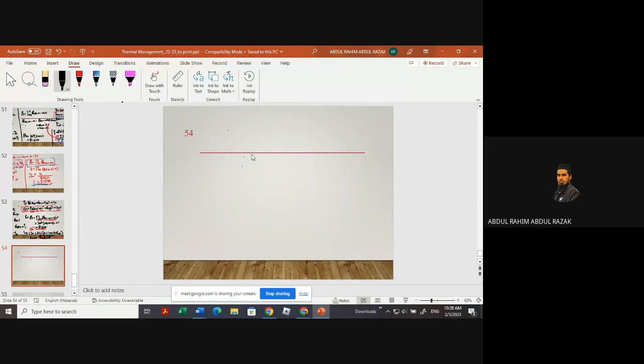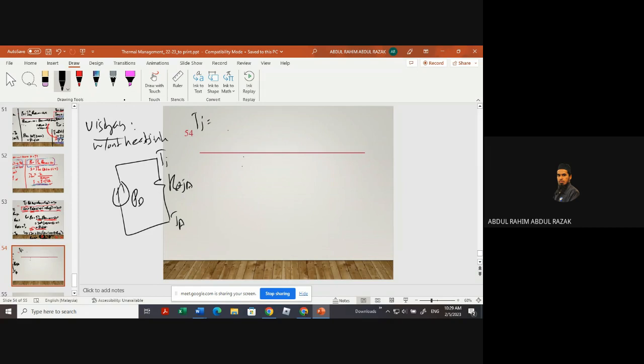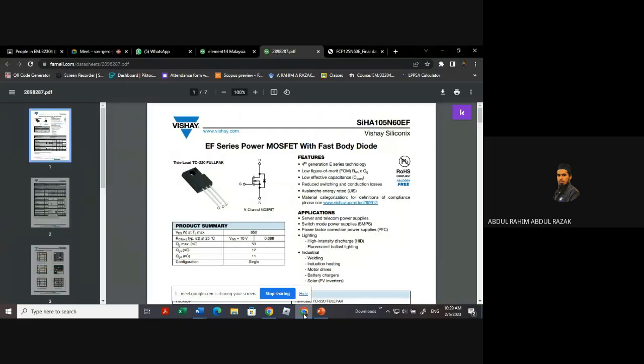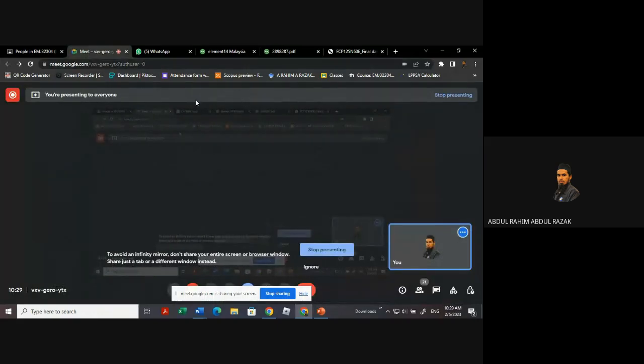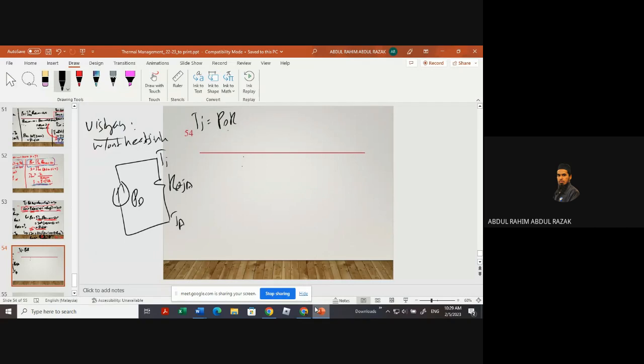Okay, now V shape. Can you get this? V shape without fixing, without heat sink. So one source and one element are thermal JA, from T junction to T ambient. So the equation will be Tj is equal to Pd times R thermal JA plus Ta.